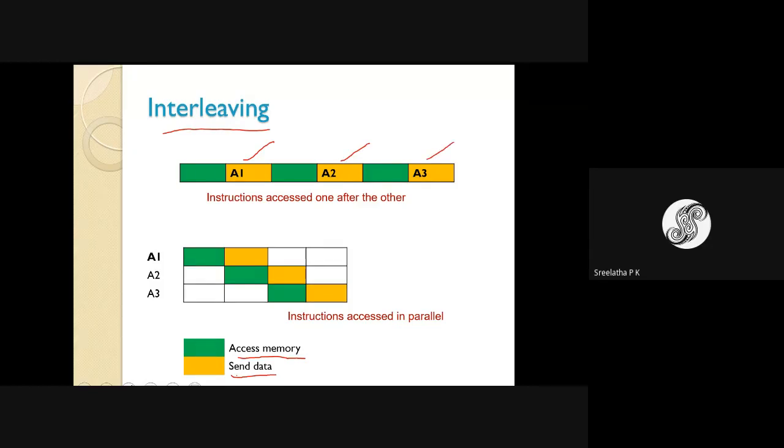And if I take that this is 1 clock cycle, 1 unit time of the processor, then here it needs 6 clock cycles to retrieve 3 instructions. In one clock cycle, the memory cannot be accessed. You have seen the row address has to be mapped, and then the column address has to be mapped. There is so much procedure.